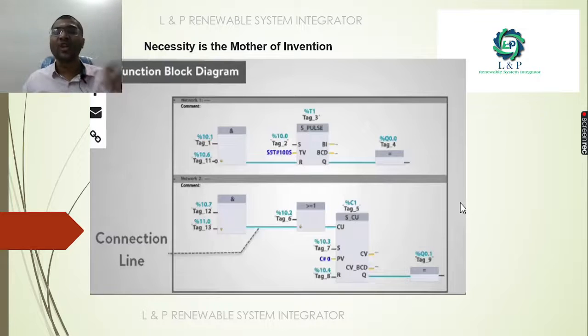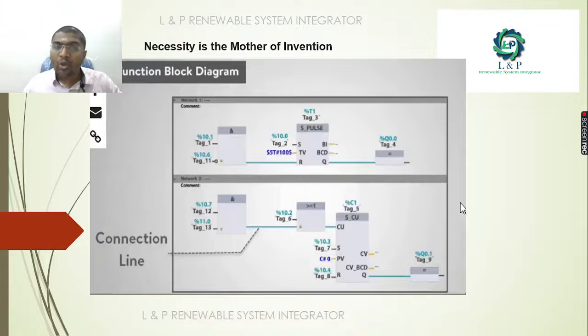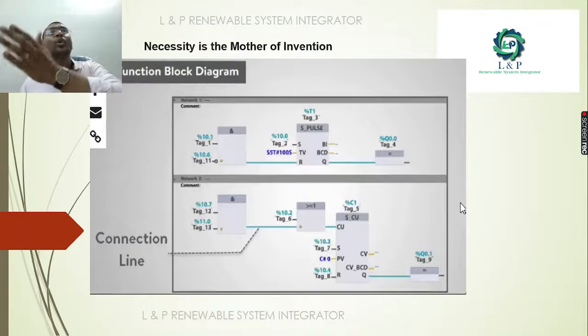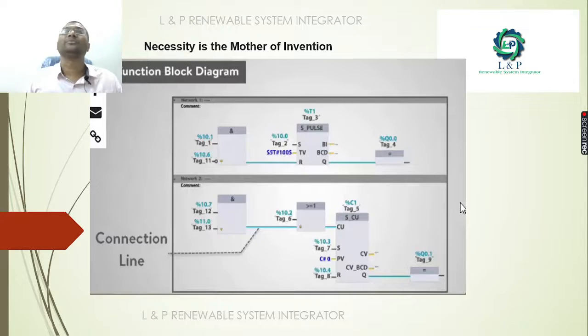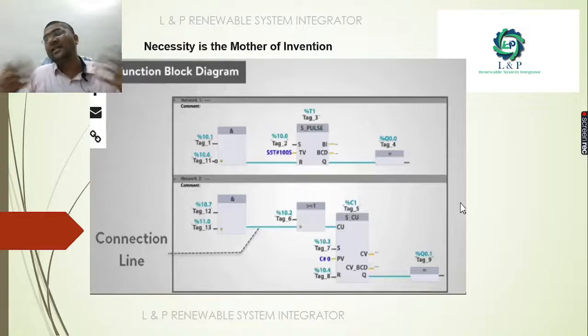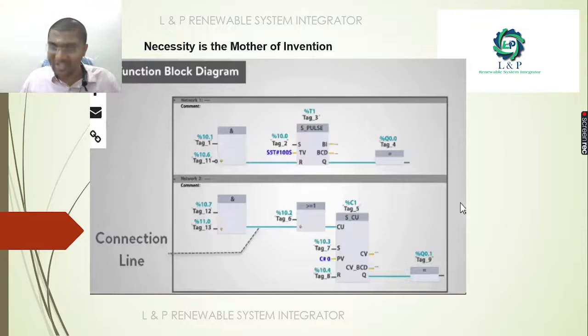In ladder logic, you can give only the addressing in one place, and if you want a tag name, you need to go inside the list and provide the tag name there, making some sort of modifications. Nowadays everything has evolved, and even inside ladder logic we can provide tag names and addressing. But the first invention was made for the function block diagram.